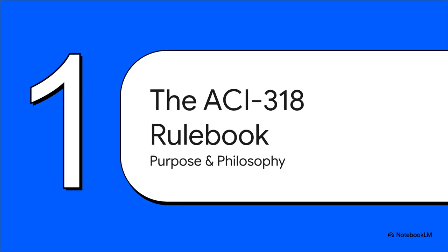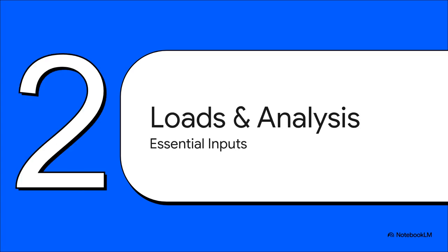Okay, first things first. You gotta understand what the code is and what it isn't. ACI 318 is not a cookbook that gives you all the answers. It's a foundation. It provides the minimum requirements for a safe design, but it absolutely relies on you to bring your professional knowledge and experience to the table. So every single design, no matter how simple or complex, starts in the same place: the loads.